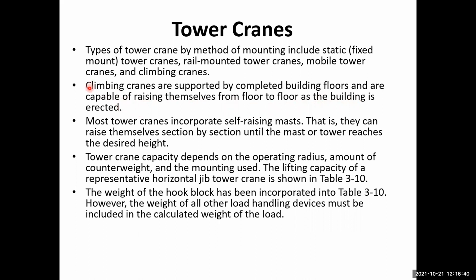This is how the climbing cranes work, and for most high-rise buildings these climbing cranes are very useful. Most tower cranes incorporate self-raising masts, that is, they raise themselves section by section until the mast reaches the desired height.